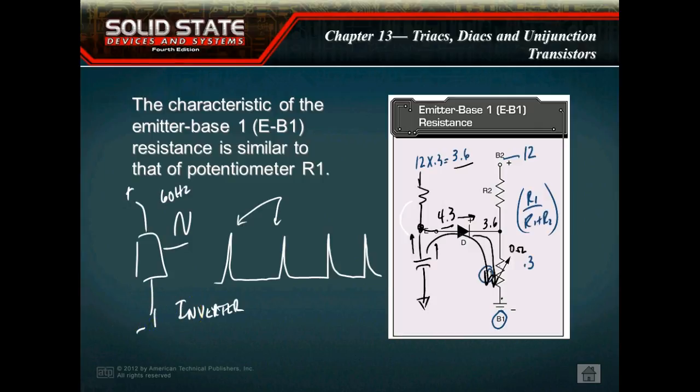But you can buy these inverters at AutoZone or any place like that. That's basically what they are, oscillators. Now, they don't use UJTs because this wouldn't be a pretty enough signal to run an AC device on, but it's the same principle. It's a device that takes steady state DC and converts it over to AC. In this situation, it would be a pulsating DC.